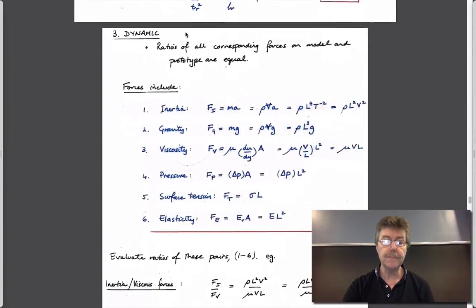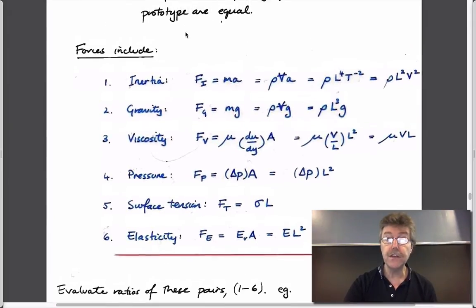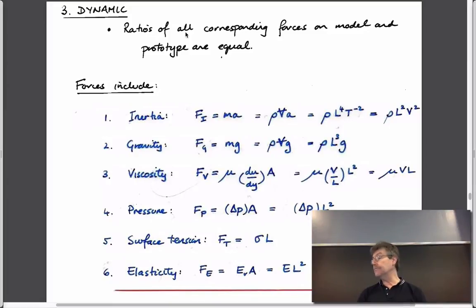I won't talk about this. We did talk about, when we chatted about non-dimensional numbers, the fact that we could look at ratios of numbers, but we actually developed ours from a Bernoulli equation, right? So we had a gravity term, which is the z term, a pressure term, which is p over unit weight of fluid, and a momentum or inertial term, v squared over 2g, and also a viscous term, this h sub l term that we deal with as well. So we had those four terms. And from looking at ratios of those parameters, we came up with things like Reynolds number, which is the ratio of inertial to viscous forces.